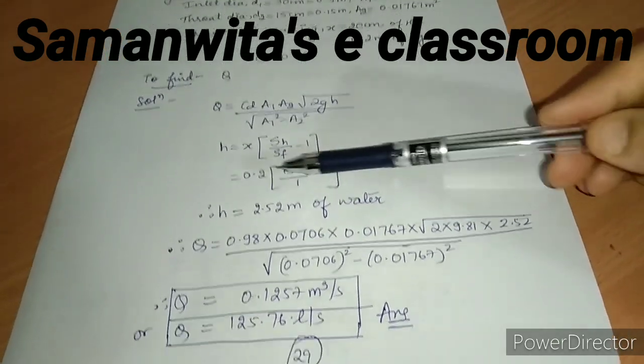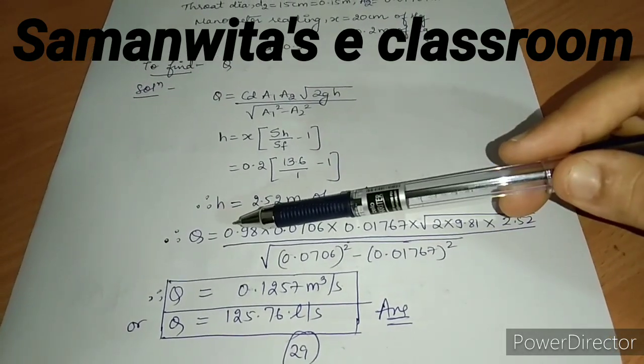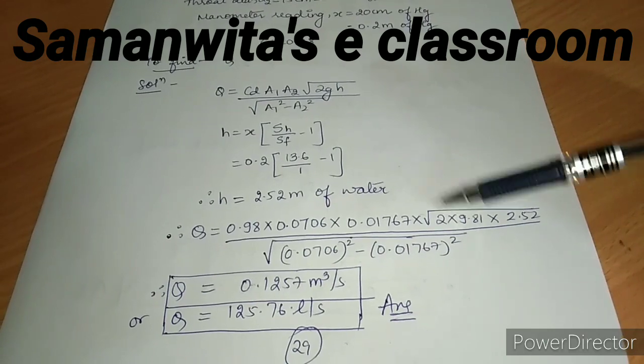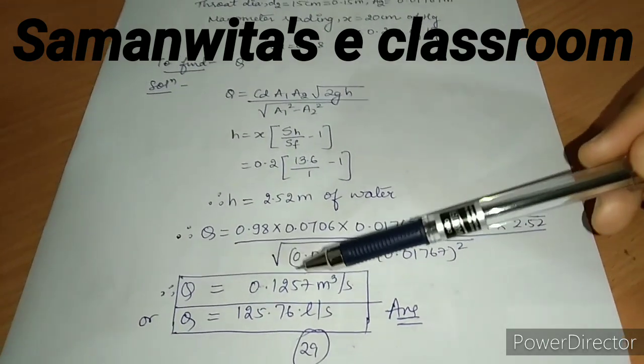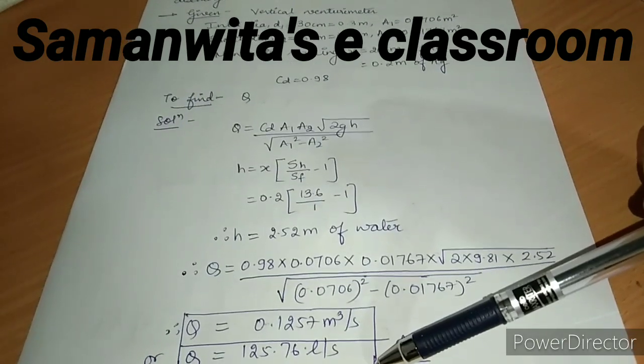When I substitute, I get the value of H as 2.52 meter of water. When I substitute all the other values in the formula of Q, I'll get the answer as 0.1257 meter cube per second. I can convert it into liters per second as well.